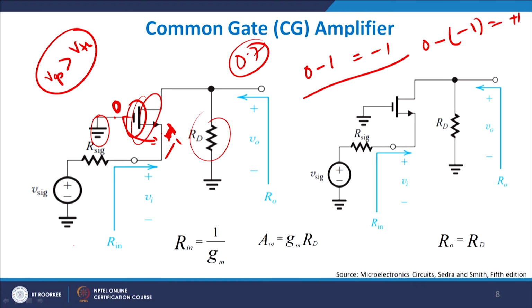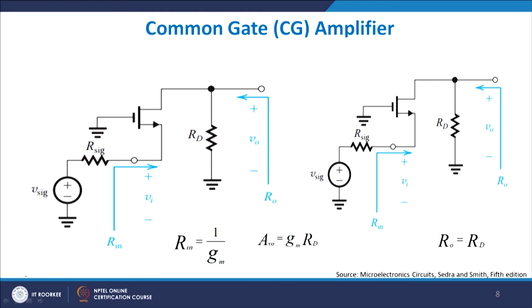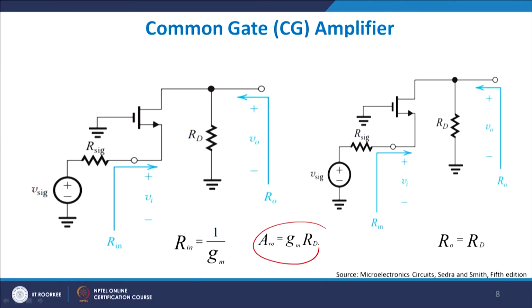So, let me remove all the inks here, and for a common gate option, I will prove it maybe next time, that in this case also I get gm Rd as my gain, but quite interestingly you do not have a phase change of 180 degrees. So, your output will be exactly in phase with the input side, unlike in the CS stage, here you will not get the same profile in this case, right. So, with this let me stop here today and explain what we have done.